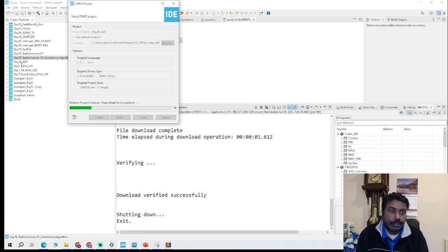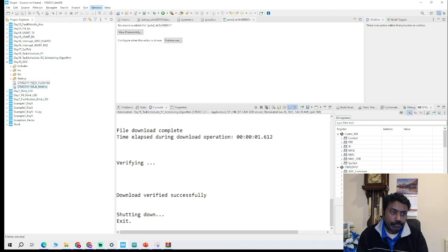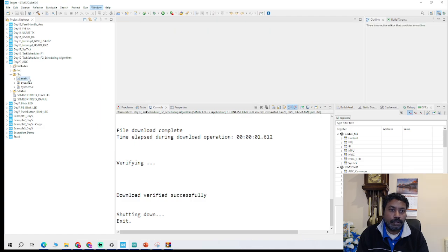This will start to produce and give the files. It's already started and it will give all the necessary files that we need to program. So we have to wait. It's on 83% settings. Okay, we are in. So click on the source code, click on source and click on main.c. I will close the rest of the program so you won't get confused.